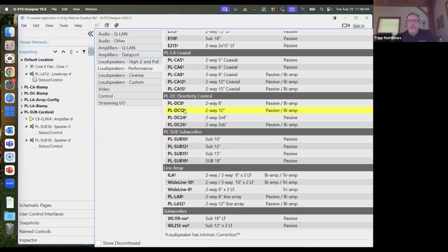And the other thing I always notice when we talk about changing these horns, because they're directivity control boxes, is that when you take the grill off and take the four screws out, the horn itself is two half shells that bolt together, and it's just the horn that comes out. So the driver stays mounted in the box. There's no need to worry about fighting the weight of a high frequency driver to get it out. You just change the half shells to whatever symmetrical or asymmetrical patterns you want. You can rotate them either way.